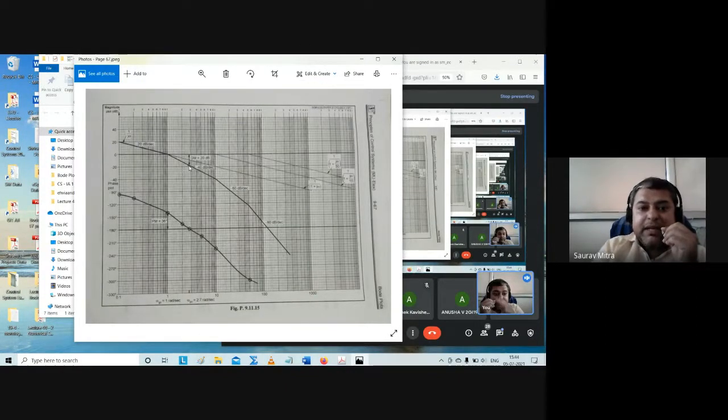As per this numerical, minus 10 dB will also work. That means whatever resultant is there, you can shift it above by 10 dB more. So how can you shift it above by 10 dB more? That means 20 log x is equal to 10. From there you can find the value of x.